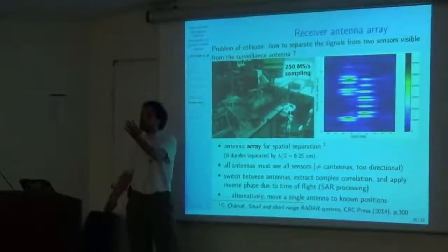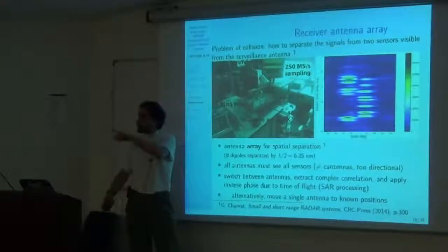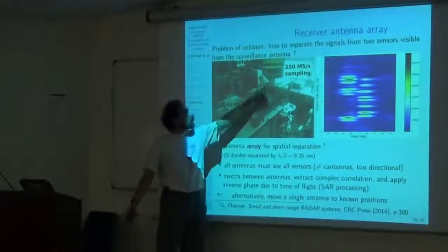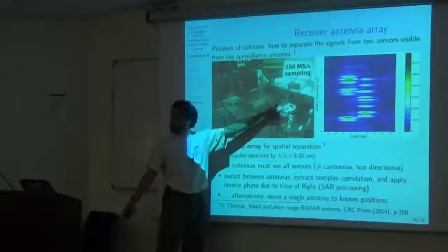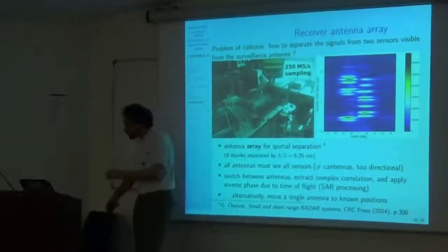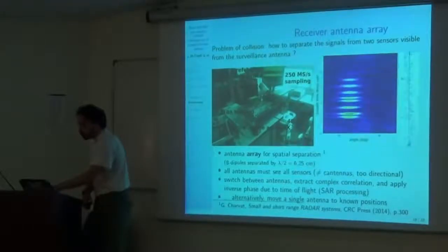So this is a really important consequence for people who have a USRP. You have one USRP, but just by using a radio frequency switch, you can measure multiple antennas one after the other, and all you're interested in is the phase between the emitted signal and the received signal at each antenna. And DOA, as was shown earlier, is just a matter of implementing a weighting function that will compensate for the phase introduced by the geometry.